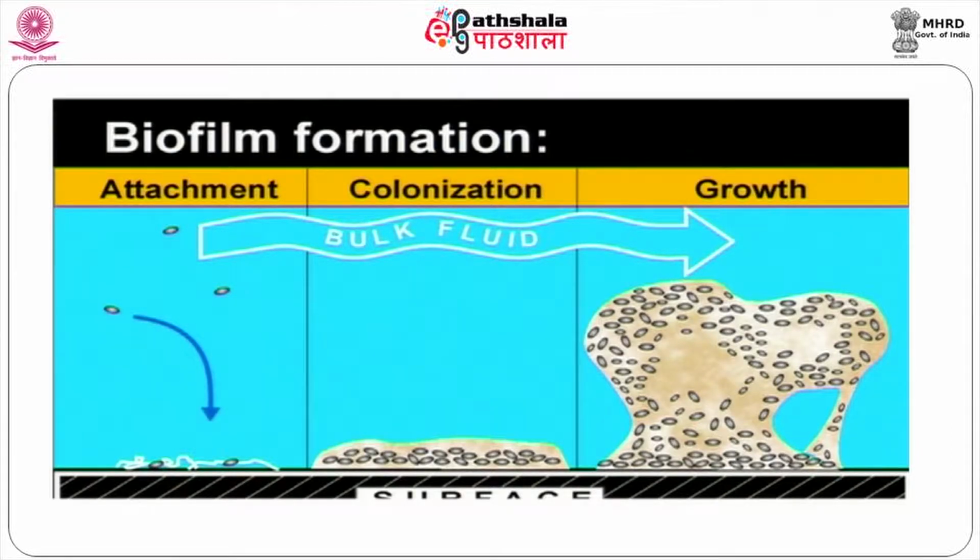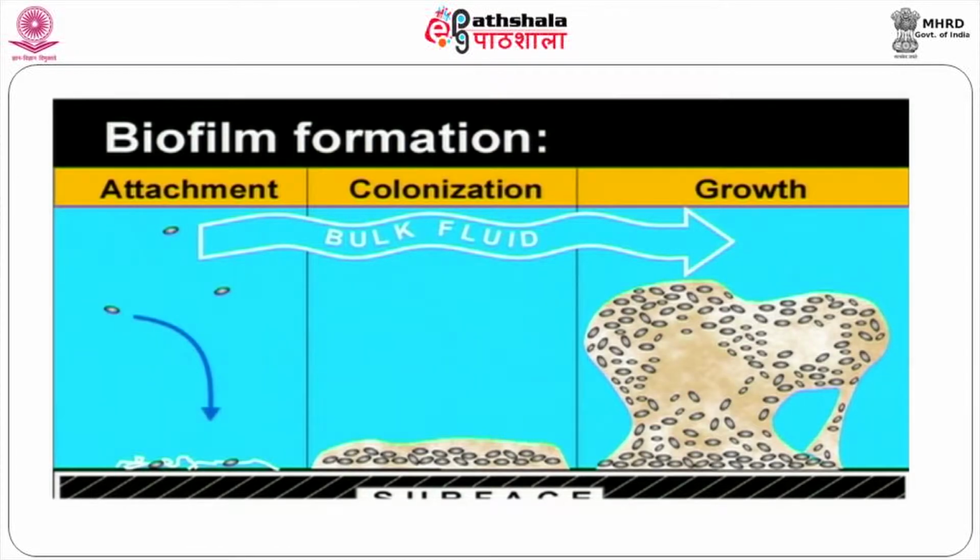This is the formation of a biological biofilm in the case of an immobilized growth process or trickling filter process. Initially, some thin, discrete biomass will be generated. The bacterial cell excretes some sort of polymeric substance, called glycocalyx. Glycocalyx possesses excellent binding property. It also possesses an exchange property. Whatever trace nutrients are required to support bacterial life will be retained there.